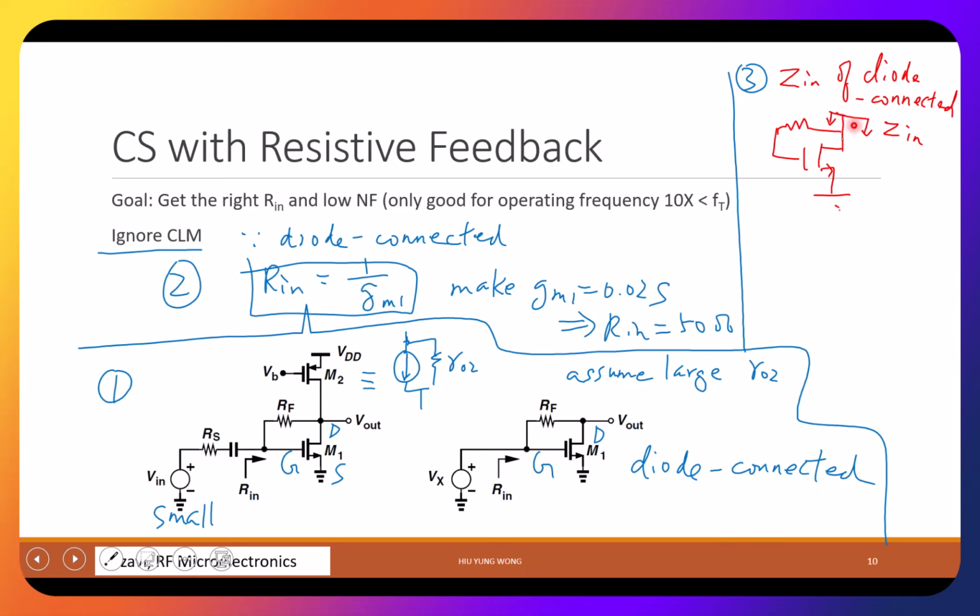Gate connected to the drain, looking down. What do you do? Small signal. Draw this guy. This is plus minus VGS. I ignore channel length modulation, so no ro. What is this? gm VGS. That's it, right? Then I need to connect them, correct?